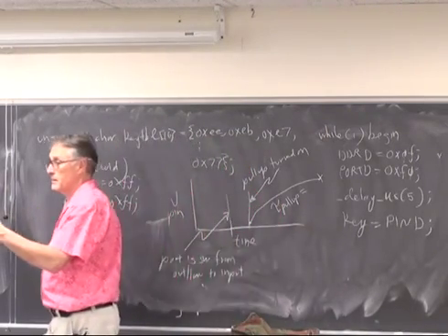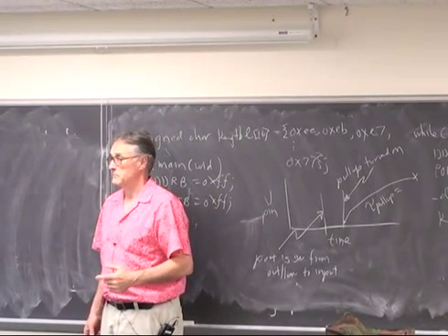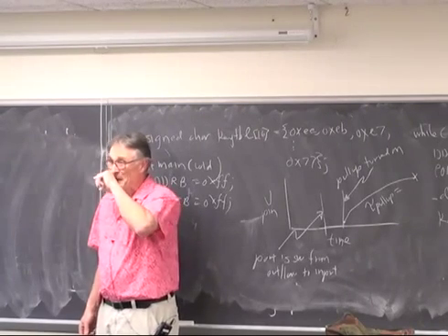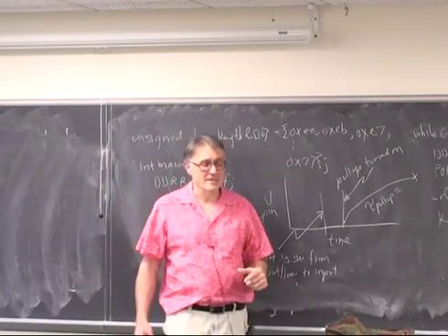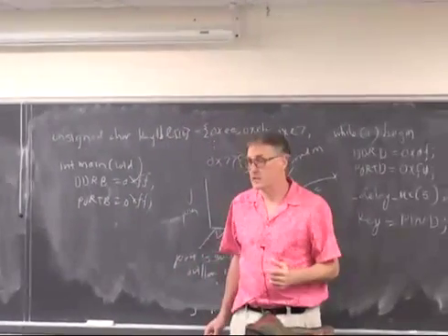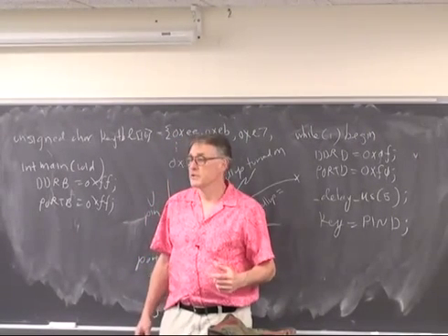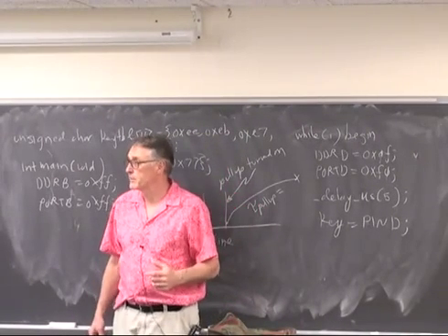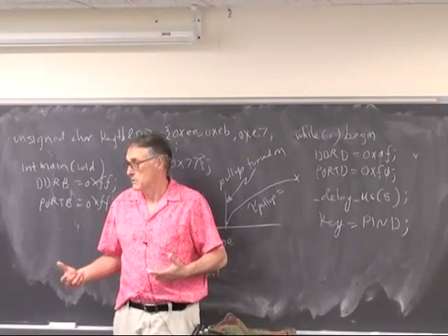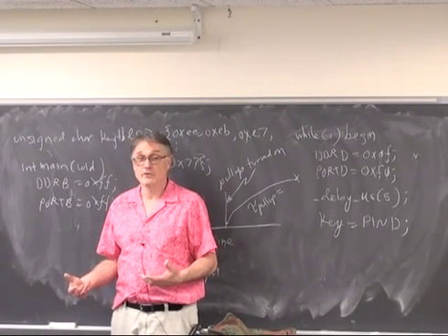I just have a quick question about the lab. For resistance auto ranging, do you need to auto range both VREF and the resistor you're using, or just the resistor? I think it is sufficient to auto range the resistor. Okay, just set the ref to 5. Yeah, set VREF to whatever you feel like and auto range the resistor, yes. Because it's all ratio measurements anyway with the resistor. So VREF actually doesn't matter. So set it to 5.